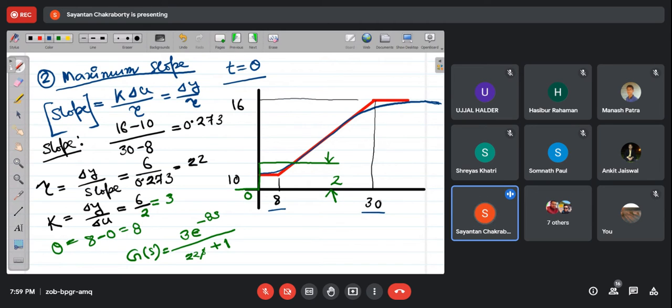Or what is the steady state value? It is not practical to wait that long to obtain the steady state value or to ascertain whether it reaches steady state or not. In practical situations, especially in chemical plants, we have some very slow reactions which take days to complete, and in biological systems as well. So will you wait for that long period to get the data? No, it's not advisable. So this is one very critical limitation of this method, especially for systems having a large time constant.